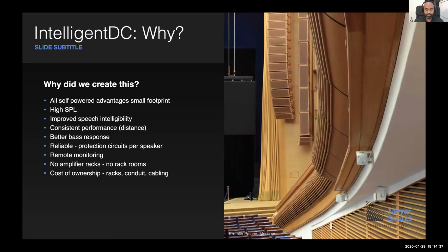Another important thing is being a low power system, a 48-volt system. It is not mandatory to put them in a conduit for safety reasons. So that brings down a lot of cabling costs and cabling hassles that come with conduiting cables. And of course, these systems are safe without conduiting.